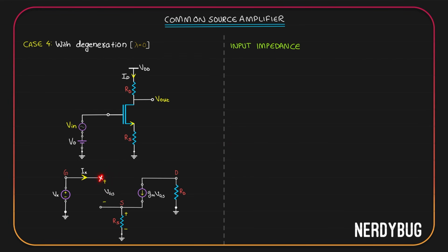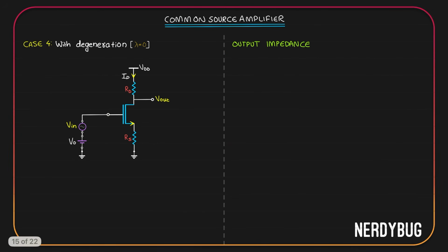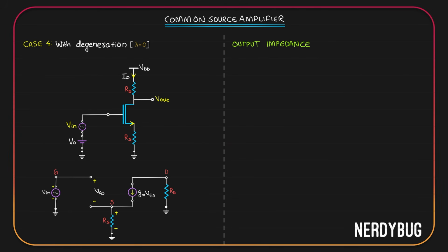The circuit is open over here, which means impedance has to be really high. But then we also have to consider the capacitance that can be there. So we will write at low frequencies, input impedance is really high or infinite. Let us see the output impedance, for which again we need the small signal model. We have to shut down Vin. Now, what we need is the output impedance, which means we will connect Vx over here and find its relation with Ix.